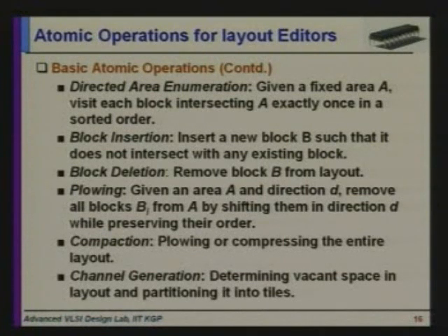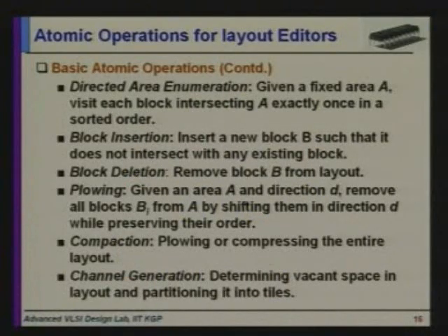So considering routing considerations and everything, if I have to place a block at a particular area, I'll remove the blocks from a particular area. I remove the blocks from a particular area in a given direction, keeping their order, and then place my block over there. Okay. Block insertion. Insert a new block B. Oh, block deletion, plowing was done. Sorry, compaction. Compaction. So we need to compress the entire layout, right? And channel generation, determining vacant space in the layout and partitioning it into tiles.